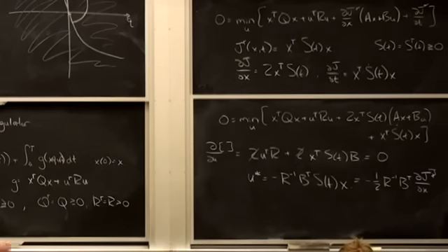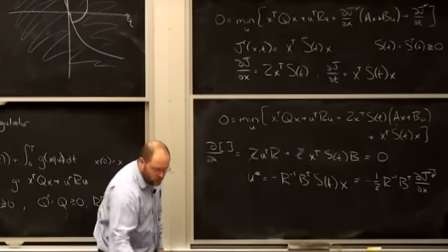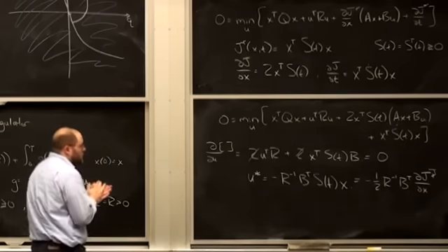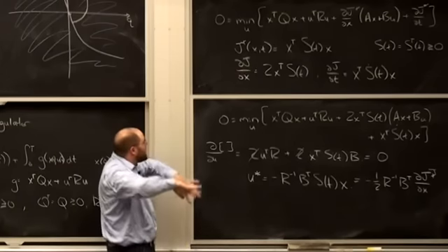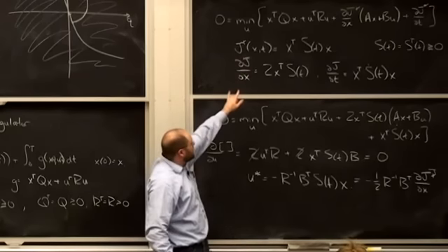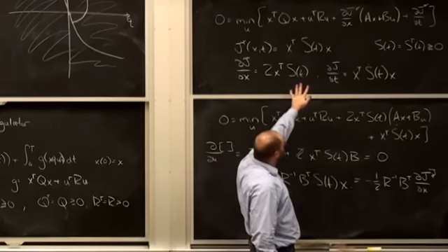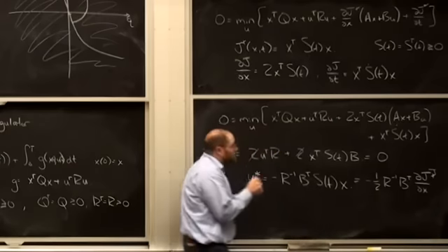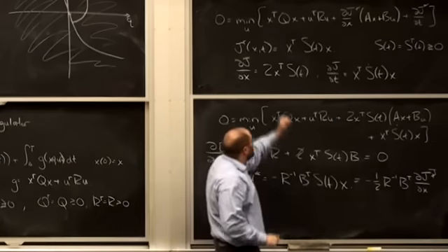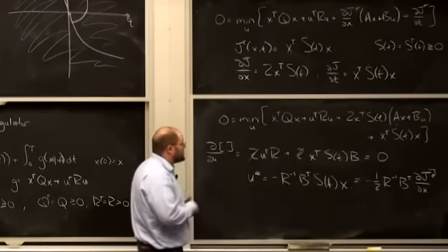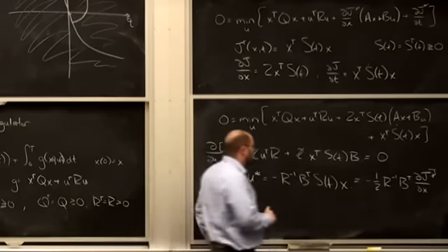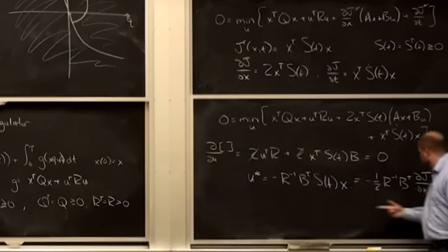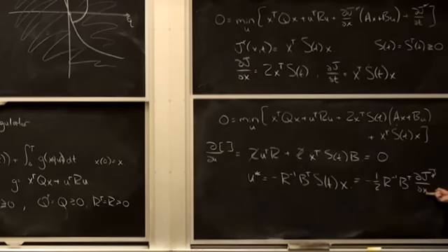Okay, so what does this mean? So I've got some quadratic approximation of my value function. Okay, it's 0 at the origin, always and forever. If I'm at the origin, I'm going to stay at the origin. My cost to go is 0, right? The exact shape of the quadratic bowl changes over time. The best thing to do is to go down. So negative of partial J partial X is trying to go down the cost to go function, right? I want to go down the cost to go function as fast as I can, right?